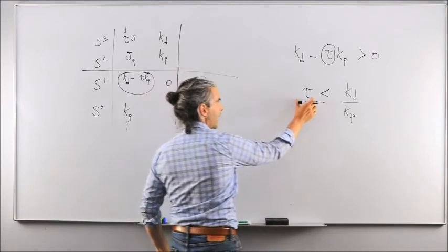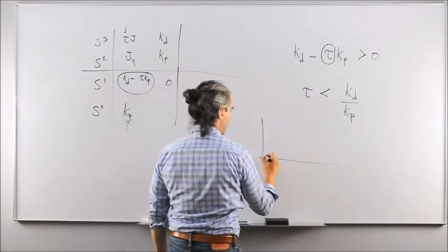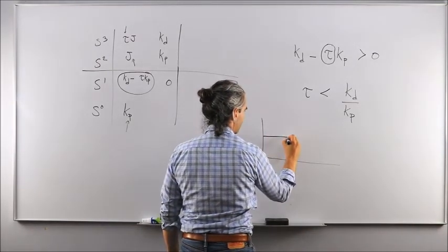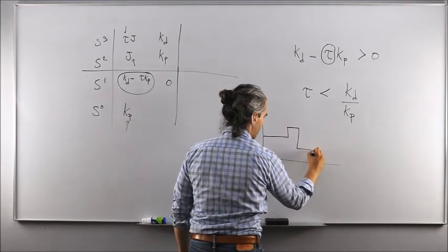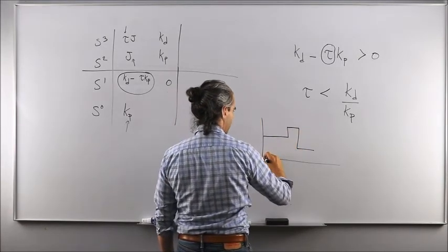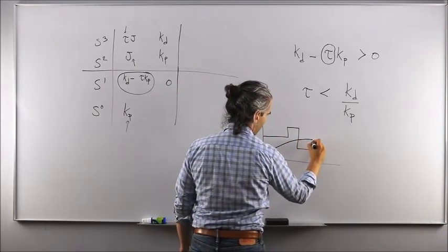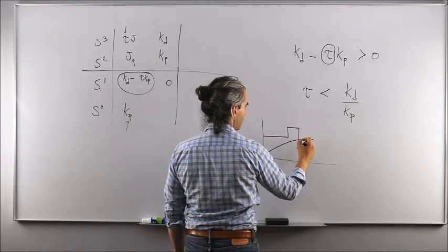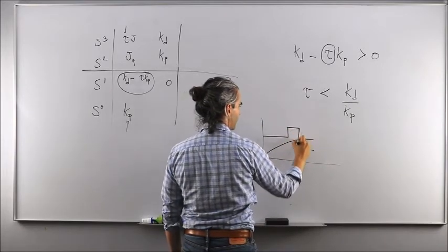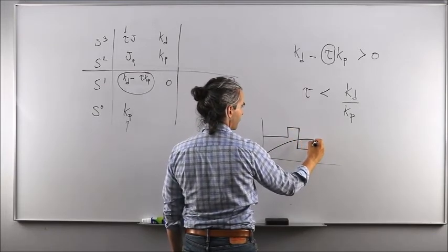Because if this guy happens to be a large number, it will mean that your controller might be demanding this, and then that, and then this in terms of a signal, such that the actuator, if it is too slow to reach the first command, boom, I reach it, then by the time we're here, it's already one step up command in the past, right?